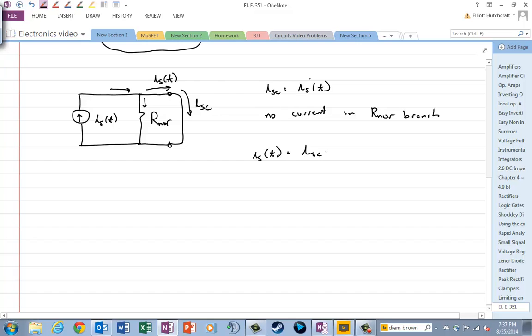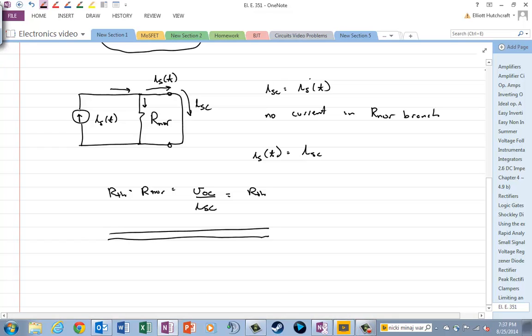And remember, what's the Thevenin equivalent resistance? When we talked about it in circuits, R Thevenin is equal to R Norton, and it's equal to V open circuit divided by I short circuit. So if you find the open circuit voltage and you find the short circuit current, whatever circuit you have, you know the Thevenin equivalent resistance. So that's sort of a brief review, and something that will be pretty important for us as we go through circuits, or excuse me, electronics.